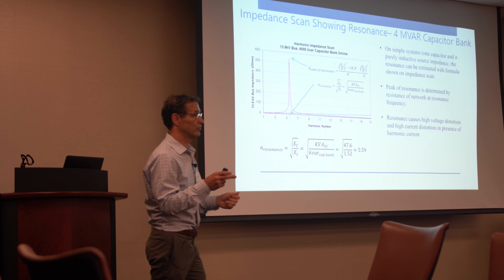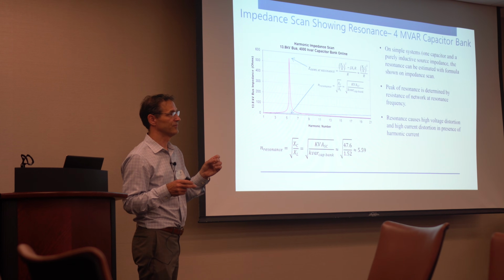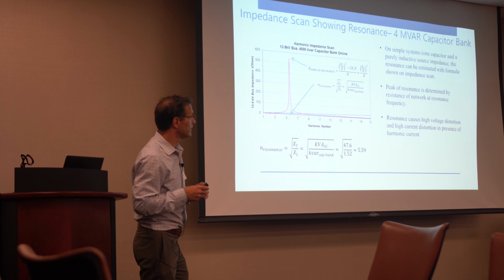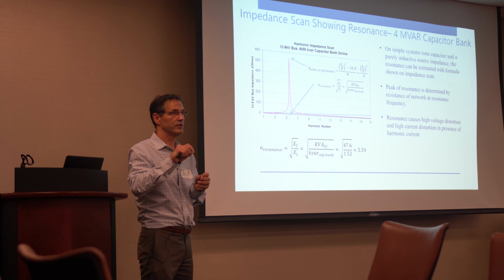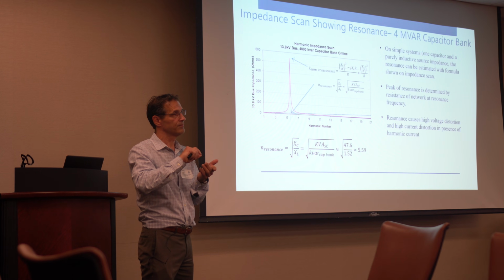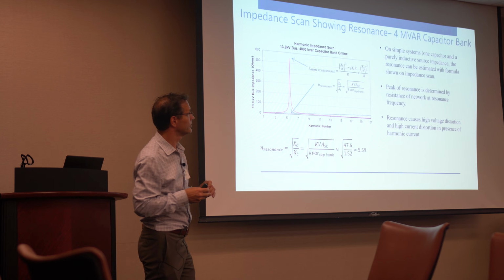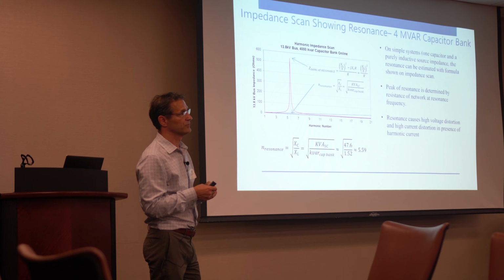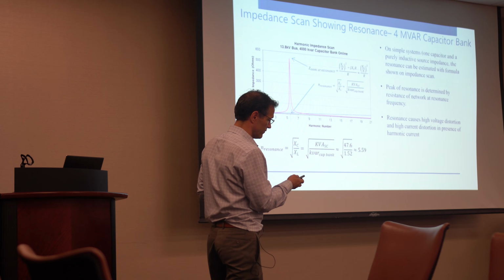So even if that drive was as perfect as the manufacturer said it was, it's still going to put out some 5th, 7th, and 11th, because the drive's not doing everything perfectly, and the network impedances are not balanced. So on a theoretical basis, with an analysis tool, you could say that it's perfect and it's not putting out harmonic current, but it is. So 1 amp of injection at the fifth can be a problem, and that's really a key point to take away from this.